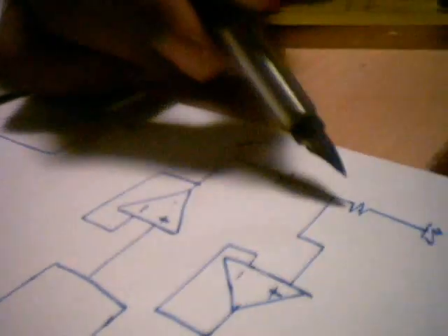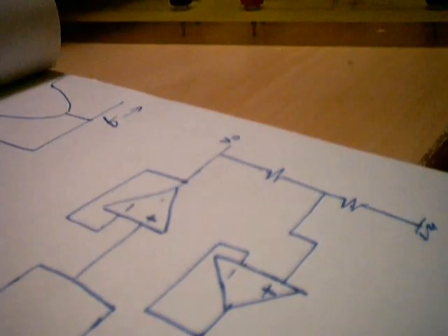So you can verify what is the Q factor. Of course, you're going to have a theoretical equation for this FL and FH, which depends on the feedback factor. So as I showed in the previous circuit, according to this circuit diagram, these two resistors will decide what are the FL and FH. So you can just verify the theoretical and practical values of FL, FH from this one.